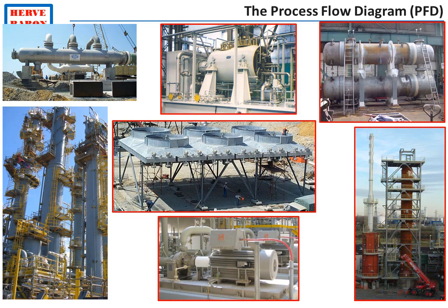For rotating equipment, i.e. equipment performing a hydraulic function, such as compressors and pumps, as well as heat exchange equipment, process simply defines the inlet and outlet conditions. Process does not perform the sizing. Process does not design, but merely specifies the equipment. The design is left to the equipment vendor. Therefore, the process datasheet issued by process is rather simple. It simply states the inlet and outlet conditions.